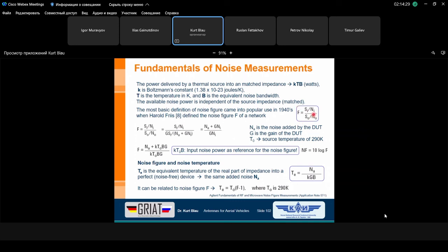But this noise power is not the same as at the input, because the bandwidth is the same, it's clear, but inside your receiver you have amplifiers which also amplify the input noise and additionally deliver a noise coming from the current flow of the active elements.